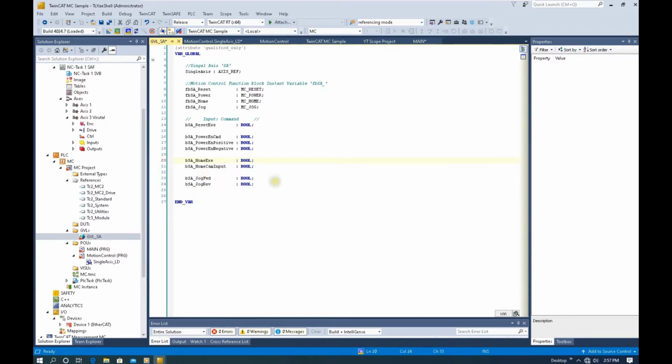They are bool commands. And then for some function blocks, we can set some variables, for example, the override percent value or the home position, that is the set position value. Those values are LREAL data type, so we can declare some variables right here. We could name them as variables or parameters. For example, the power override, home position actual value, set position value, and the jog velocity.